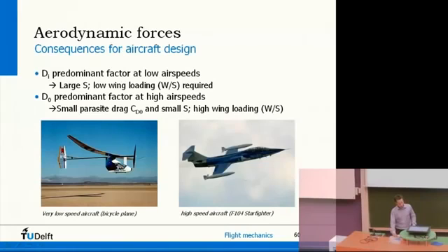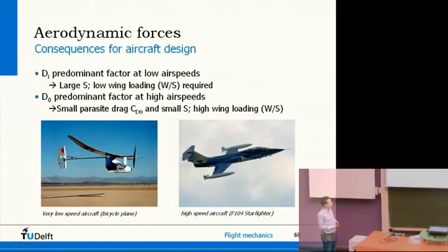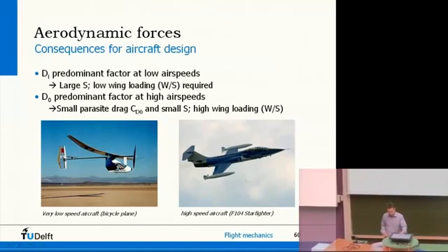If you look at aircraft, on the right hand side you see a Starfighter, an aircraft that can fly about Mach 2, so it goes very fast, and that means that aircraft only needs very small wings, because you're going fast anyway, so you have dynamic pressure to create lift. If you made a cross section of the wings, so you'd cut the wings in two and have a look, then it looks a bit like this. So these are very sharpish, thin wings that have very low friction drag.